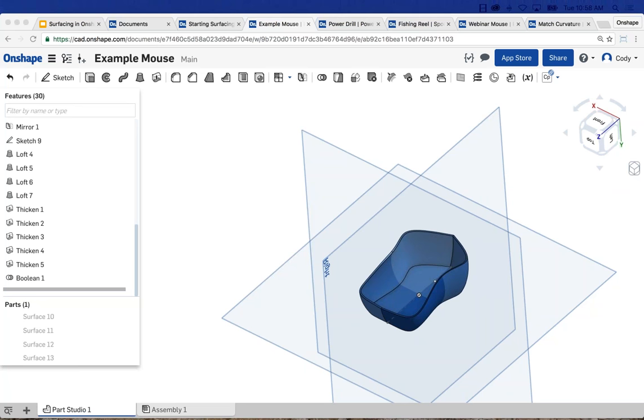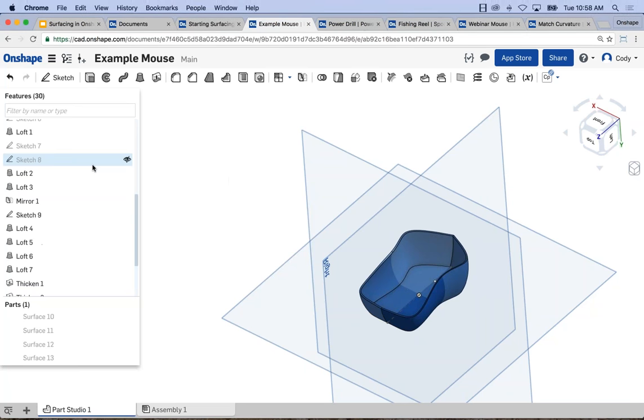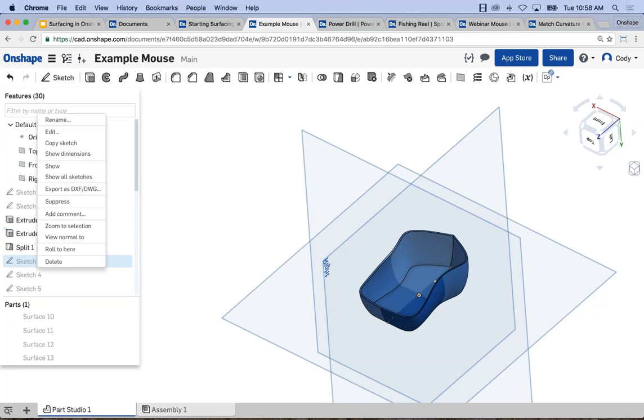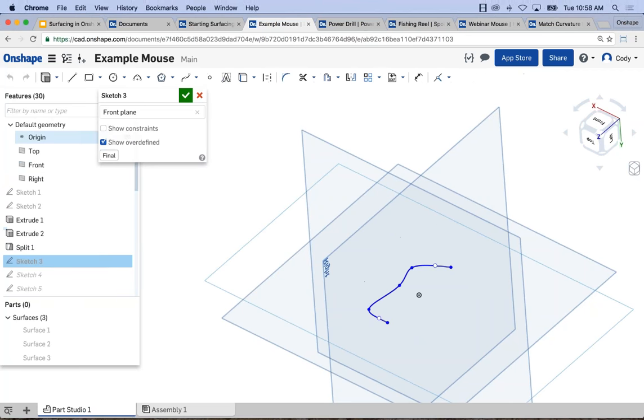I don't know if you have time today, but notice all your surfaces have creases at the mirror plane. Can you go back through and redefine the splines and resulting surfaces to make sure they're normal to the mirror plane to eliminate these creases? Yes. I can go through and define these splines.